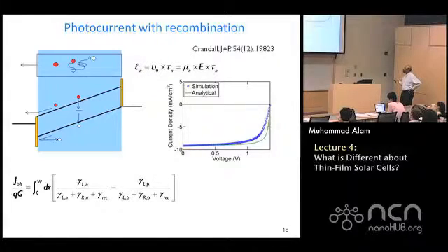Because as soon as the electron-hole pair is generated, this electron-hole pair is going to randomly walk around. It is very soon going to find a hole that has also been generated, and it's going to recombine. How far is it going to go before it recombines? Well, this time to recombination depends on how many defects I have and the velocity of it. And the electron's velocity will be mu multiplied by the electric field, mobility multiplied by the electric field.